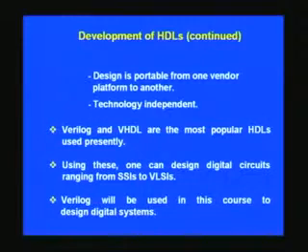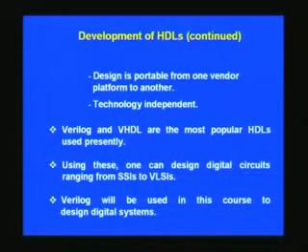It is needless to emphasize that Verilog and HDLs can be used in circuit design ranging from SSIs to VLSIs. So you may regard up to 500 transistors as falling in the SSI category, beyond that and below 5000 for MSI, and beyond 5000 up to 50,000 as LSIs, and beyond that they are termed VLSIs. These are the numbers of transistors I am speaking of. We will be using Verilog in this course for digital VLSI system design.